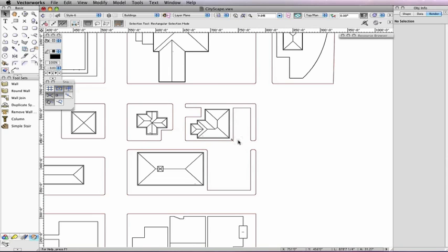Keep in mind that smart points can only be acquired based on existing snap points, so for that reason you must have at least Snap to Object enabled in the snapping palette to use smart points.